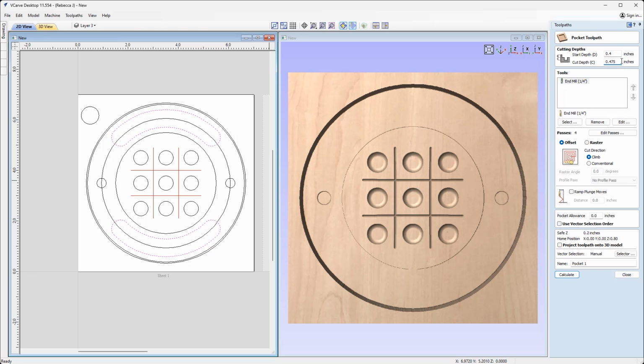Now it's crucial that for both pieces that have the troughs, we ensure that we have enough room that our marbles can actually fit inside. So we want to make sure that our depth of cut is suitable for our marbles. On this side, I'm going to go in at 0.475, and I'll still have a little bit of a gap of material left underneath. And then we'll figure out the ring trough shortly when we come to that sheet.